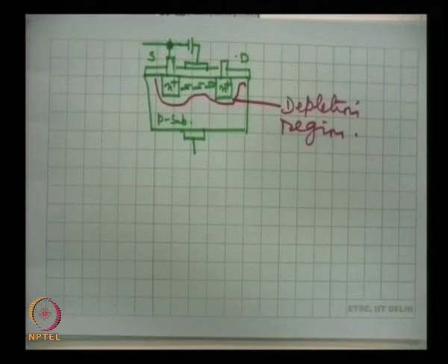Wherever N and P type semiconductors meet and there is structural continuity, a depletion region has to occur, it always occurs. What gives rise to this depletion region? The natural processes of diffusion and drift, as we discussed in the case of PN junction formation.